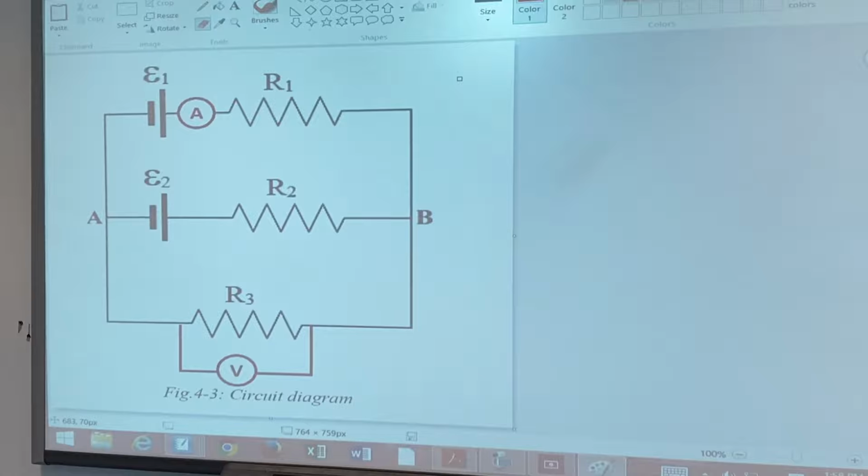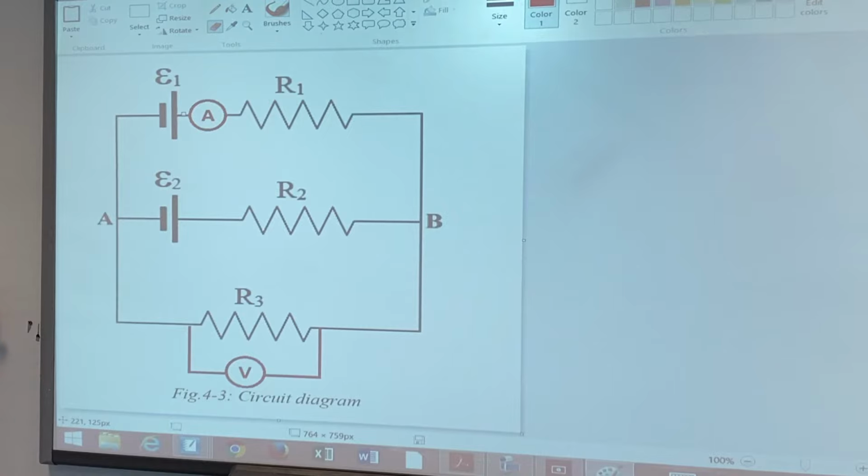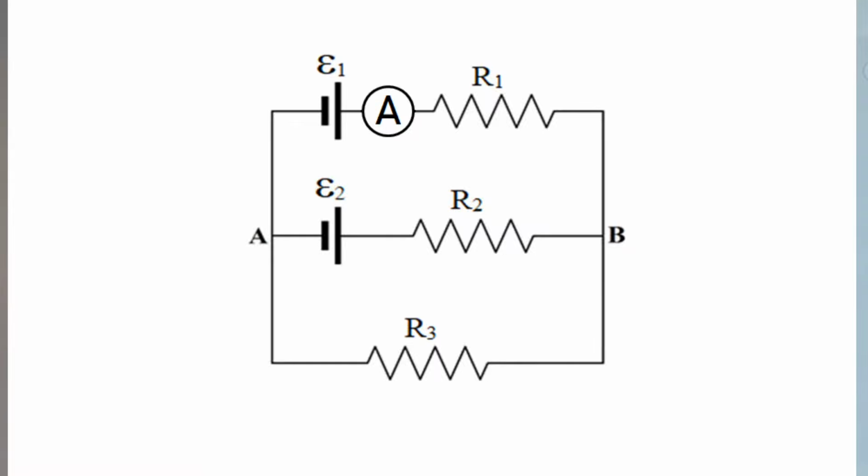Your task in this experiment is to measure the current in part 1 in the 3 branches: the first branch, the second, and the third branch. So here in this example, we are measuring the current in the first branch of our circuit. Notice how we have to cut the circuit and insert our ammeter. This can be the ammeter or it can be the current sensor as well. Both of them should be handled in the same way. In other words, they should be connected in series with your circuit. Otherwise, you may end up burning the current sensor or having very bad results.